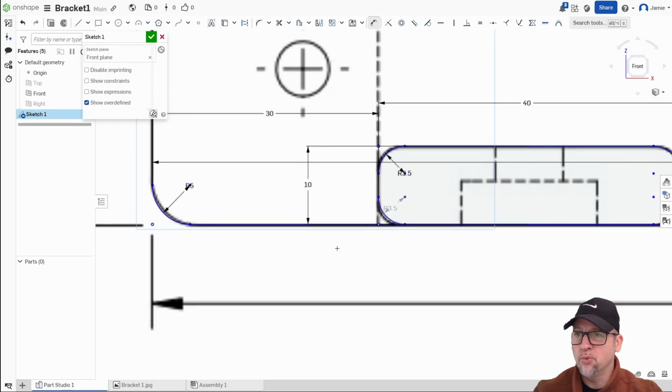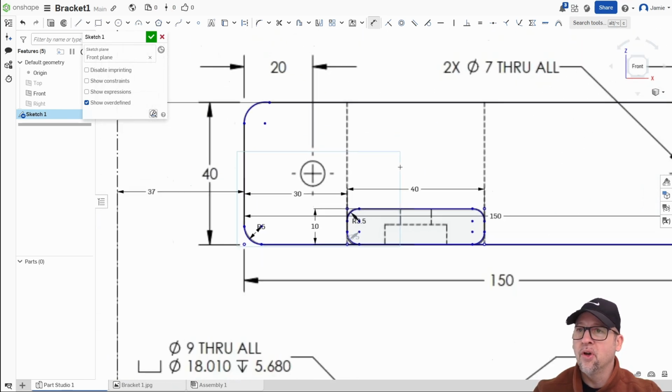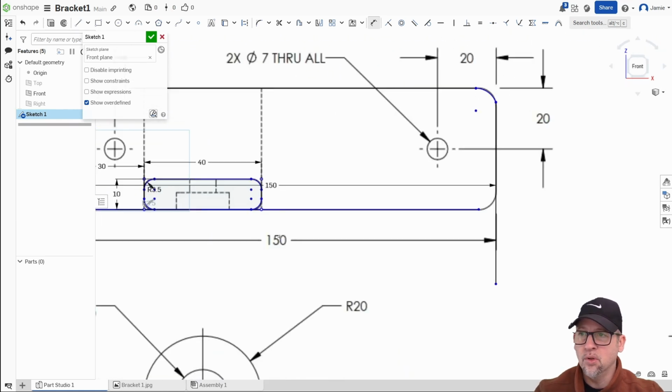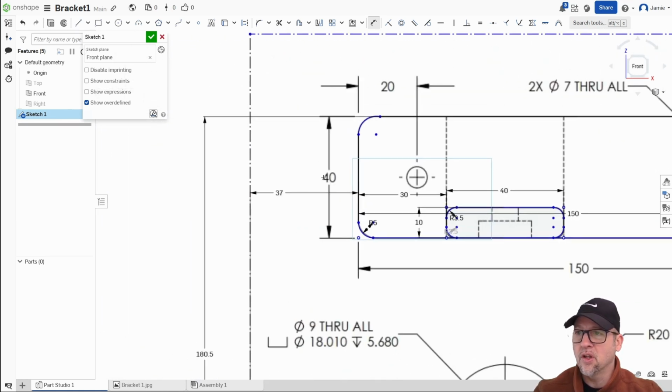All right, radiuses I'm not so concerned about, and overall size. Okay, this one is blue. Here I can get a 40 here. Is that my 40? No, that's not my 40. So if I put my own dimension here, I can say this is what's okay. Space bar will get me out of it. Let me try it again. Black line to blue line, and then 40 millimeters. There we go. Matched up.